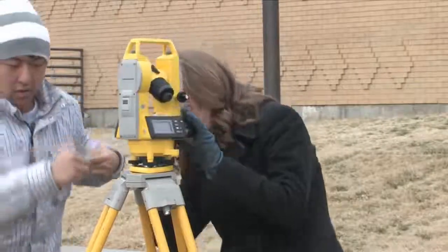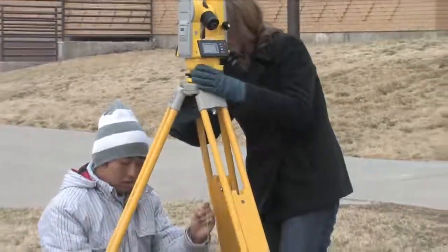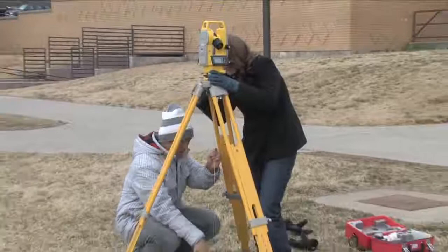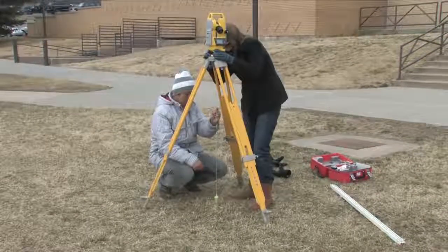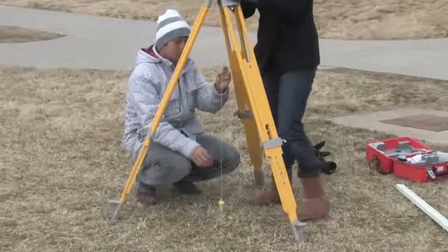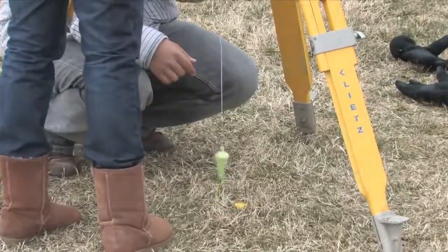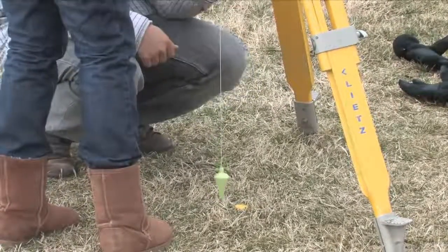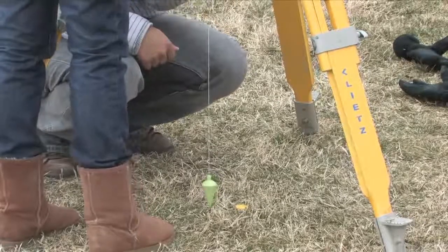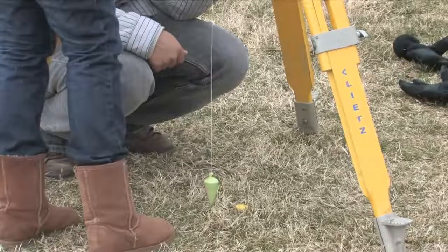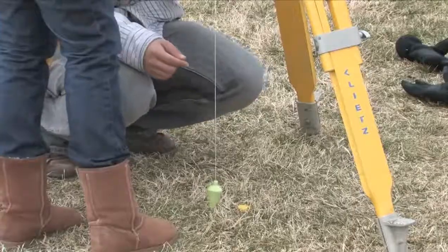Once the height of the tripod has been made comfortable for the team, it is important to make sure that the instrument is directly over the traverse cap. To do this, place a line of the plumb bob through the hook and the bolt of the tripod. Then gently extend the plumb bob line down towards the top of the traverse cap. Observe the location of the tip of the plumb bob. If the tip of the plumb bob lines up directly with the center of the traverse cap, you're done. If not, adjust the theodolite's location on the top of the tripod accordingly until the tip of the plumb bob is directly centered on top of the traverse cap.